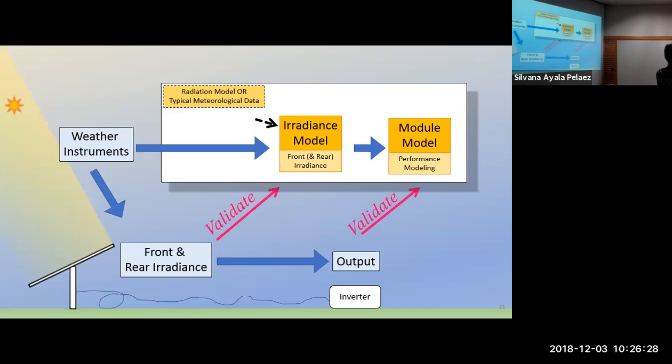Yes. So the performance modeling, is that based on manufacturer specifications for module performance, or what is performance modeling? Yes. So the performance modeling, it's using the single diode model for the module. The issue here that adds a lot of uncertainty is that the specifications that we use are usually from the producer, sometimes from national labs, and they usually test 1 or 2 modules, and we assume that that is the same behavior that all of the other modules are going to have.